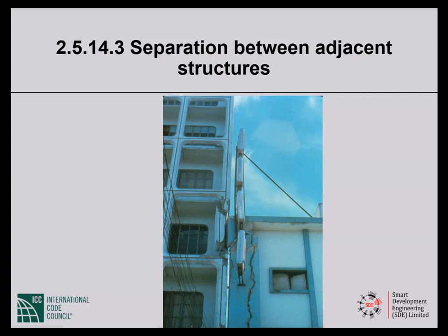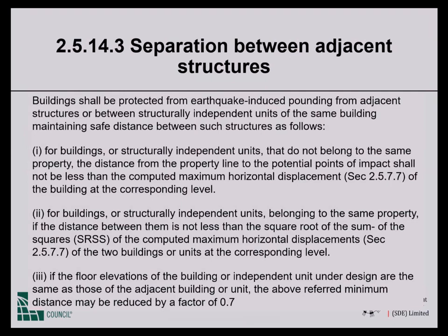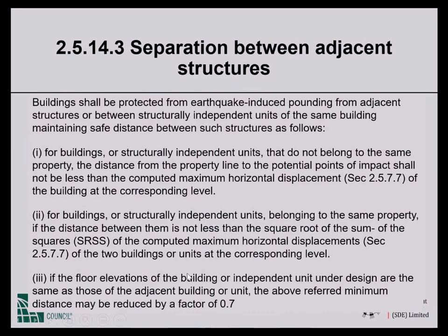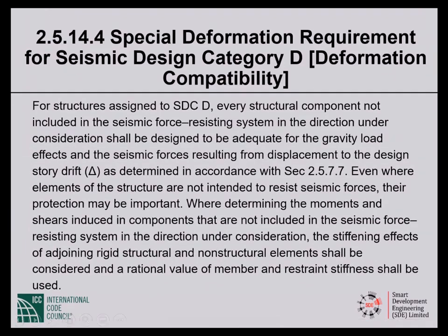Okay, so that does justify a decrease in separation distance, and this 30% probably is pretty sensible. So I kind of like this addition that BNBC has made to ASCE 7-05 requirements. Okay, this is also something very specific in BNBC 2020, although this is in every sensible code and standard you will ever see on seismic design.